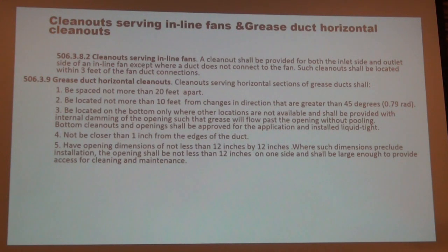I had an inspection about a month ago, and they used the grease wrap, and you know the steel bands that you secure the grease wrap with? They had the steel bands going around the access doors. And I said, no. I said, get the manufacturer instructions of that grease wrap. They show you how to make the access door.